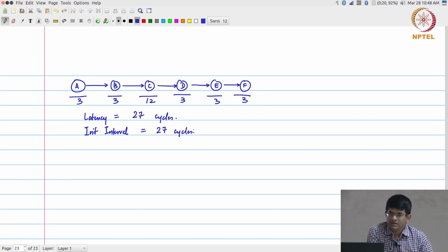Okay. So now the idea of software pipelining, which is also called task level pipelining, and in the context of HLS will actually be known as data flow pipelining, says that if I had separate pieces of hardware for A, B, C, etc., how would I go about doing this? How can I actually implement this? But let me consider another example to show that this can be applicable even in the context of software itself, and is in fact used like this in many kinds of processors. For example, the TI DSPs can make use of this kind of software pipelining.